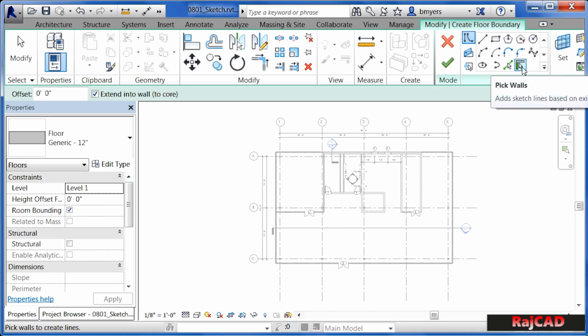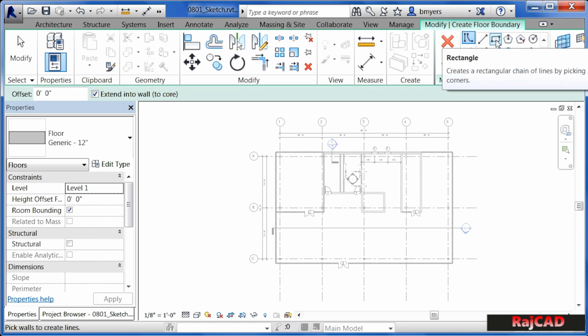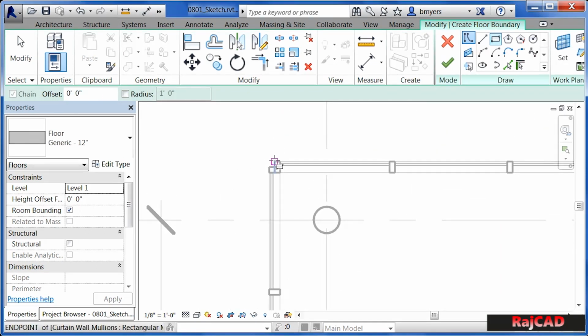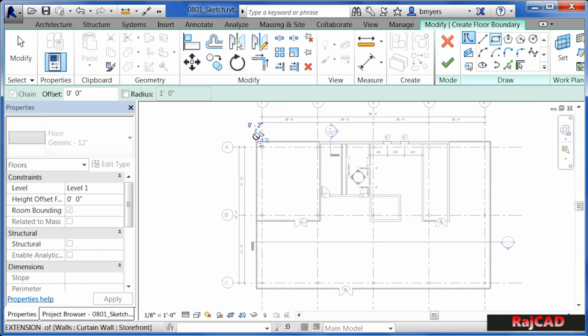Check your drawing tools, and what we're going to do is draw all the way around the perimeter of this with the floor. Now, structurally speaking, this probably isn't the best thing that we could do, but just to demonstrate how floors work, this should work really well. Move up here and select on the Rectangle tool. And you notice that you can't really pick on the intersection of these two spots very well. So just click at the intersection of one of these. We'll adjust it after the fact.